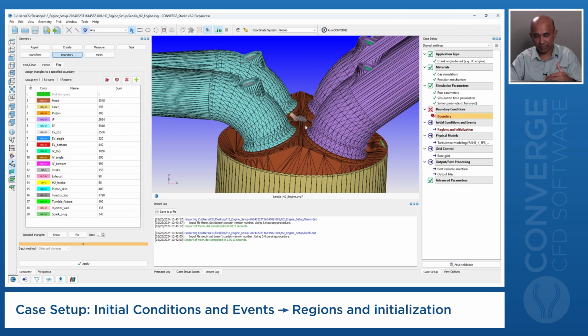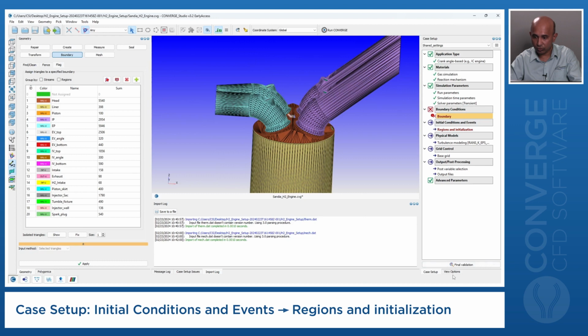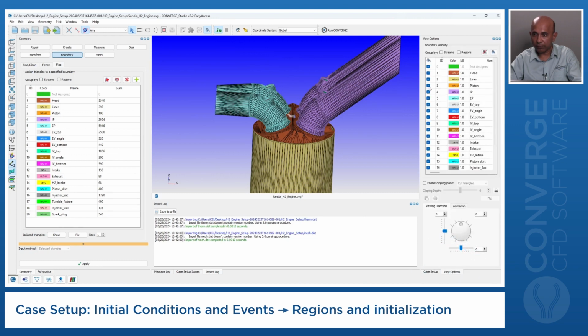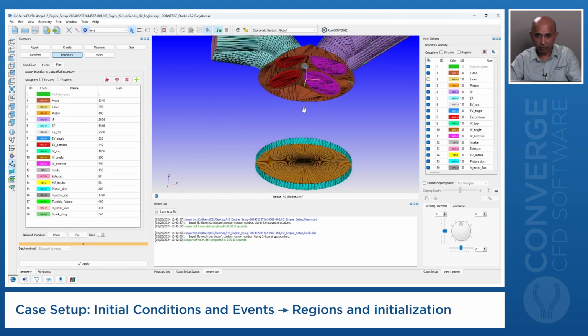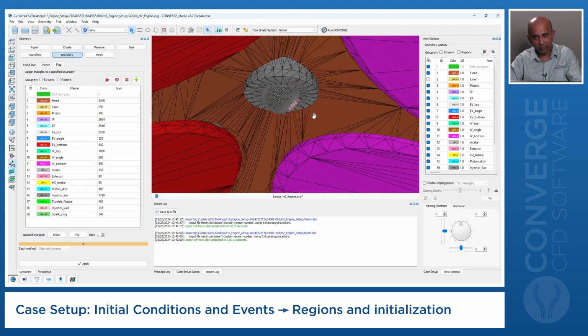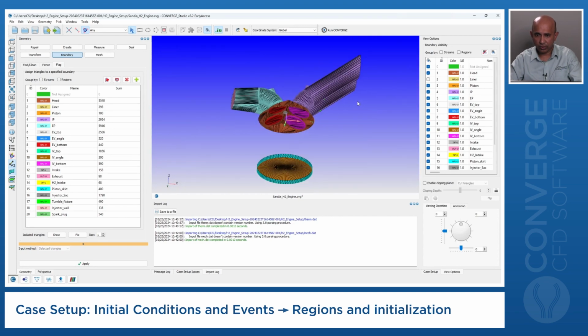And because it's a gas injector, if I remove the liner and look from here, there is no physical partition, and in the code we need to tell CONVERGE to put a physical partition here. This is called the disconnect triangles if you have taken an engine class. In order to do that, the cylinder region and the injector region need to be 2 different regions. Okay, so let's go and set that up.